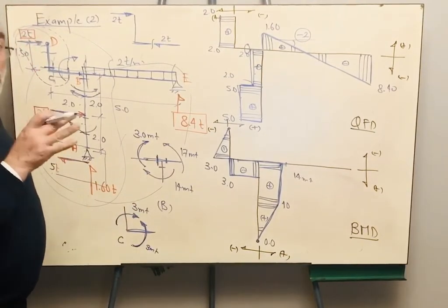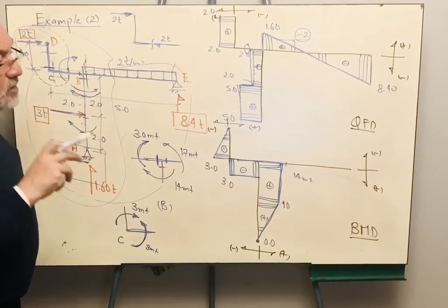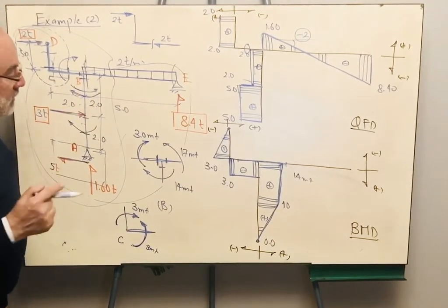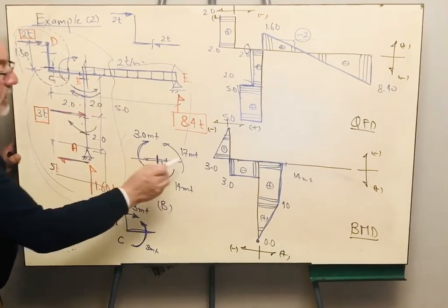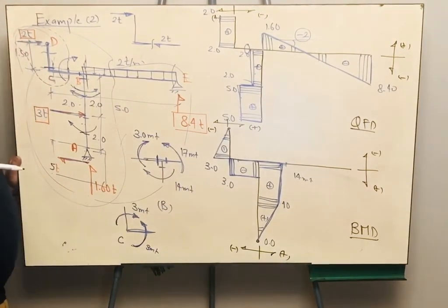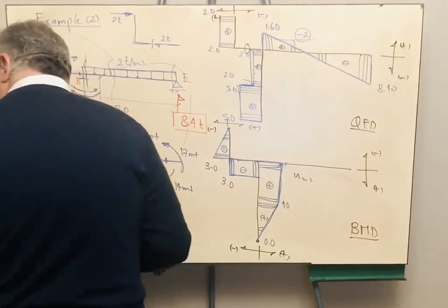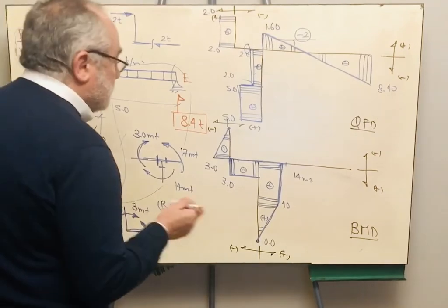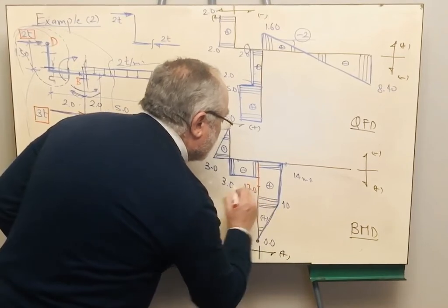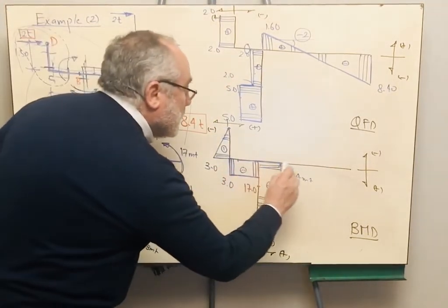So I'm very much concerned about the direction where you are drawing the bending moment, because this will define the location of the steel reinforcement, as we said before. But let's proceed. On the right hand side of point B, we have a moment of 17 meter ton. Where is the tail of the arrow? It is below the datum. Therefore I will come here. Let me draw this with another color so that it is clear. I have here 17. Very good. This is drawn perpendicular to the datum.